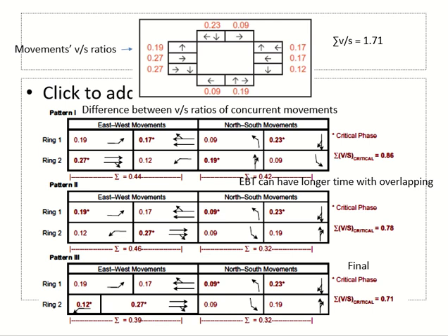So we discussed two principles here basically. The first one was the easiest approach, which is each lane group has a phase. Then you do the summation, simple summation, and you get this one. If it is practical, fine, you can stop here, no problem. If not, the second easiest approach is every direction has a phase, all movements in that direction together. Left turning and straight together, left turning and straight together. You do the V by S ratio. It's this much here, but it could be anywhere.